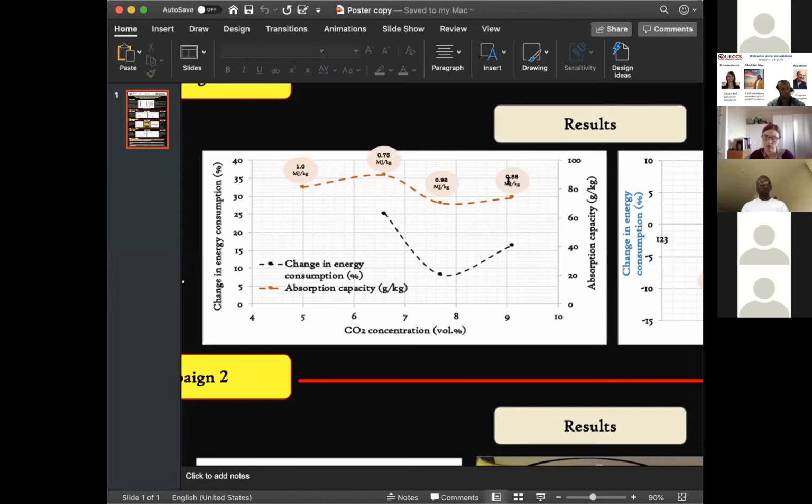That's one. Secondly, with selective exhaust gas recirculation, the solvent flow rate increases. Therefore, your solvent inventory increases. Therefore, the cost of the solvent management and the cost of the solvent disposal increases.